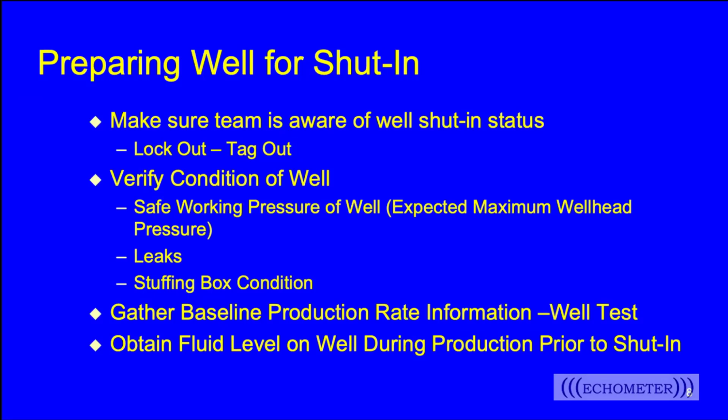Now we need to be especially vigilant on our older wells, where the wellbore integrity might not be very good. We might want to consider something else. If we don't think we can close in the valves, and the wellbore won't withstand that pressure, perhaps we can try leaving the valves open, and hopefully the liquid production in the well will kill the well, and we'll still be able to obtain a static. But in general, we prefer to have the well shut in to obtain our static bottom hole pressure.